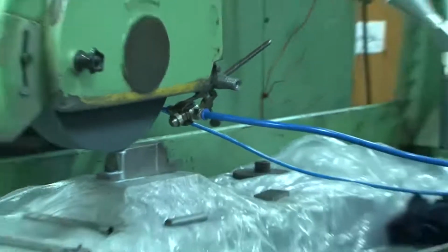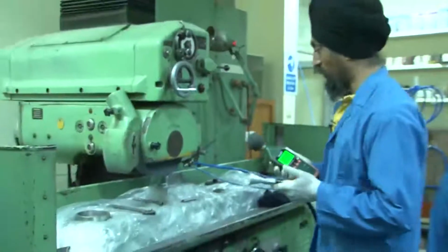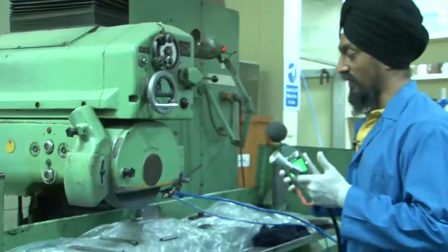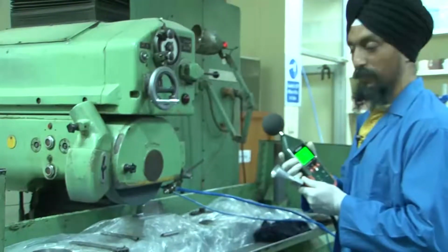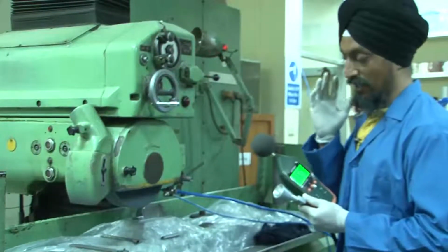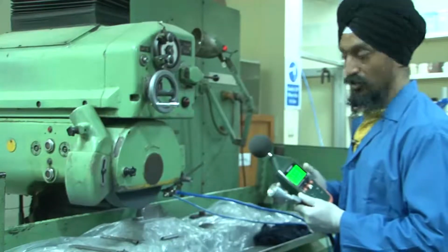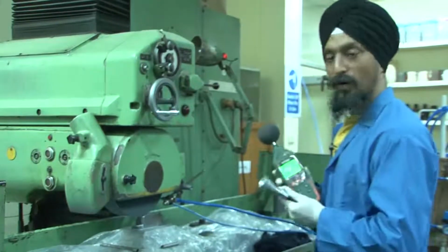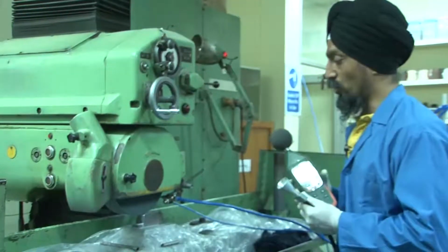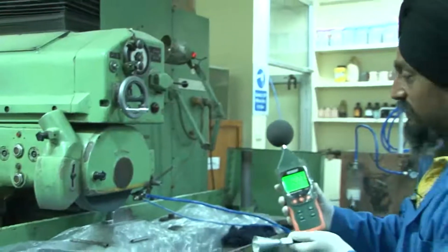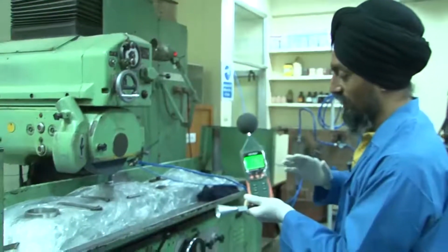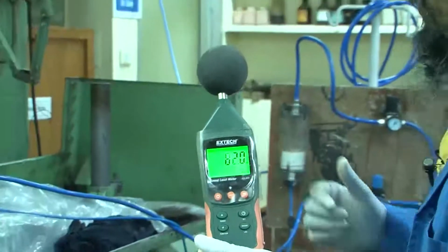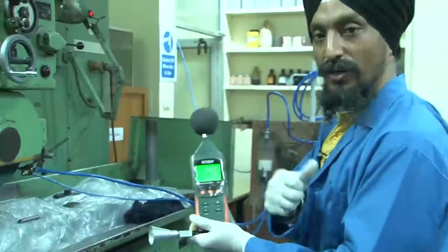These instruments are just a makeshift arrangement here. They are generally fixed at a distance so as to represent the human nose and human ear. For example, I am here. This distance is identified as 500 millimeters. I'll hold it here and record both things while machining: what the sound value is and how it is changing, and I'll switch on the air particle counter, which will also record that. So we could start the machining, and the data would be recorded in our LabVIEW software.